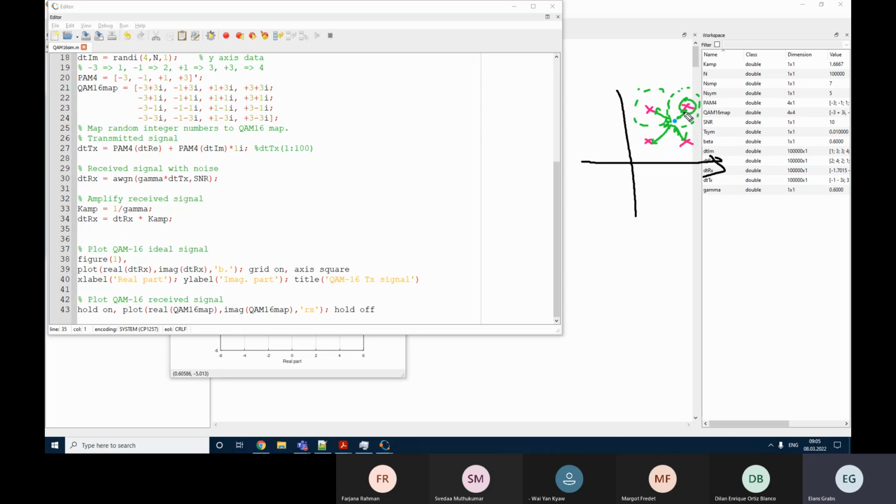But of course, if noise is too high, sometimes a situation can happen like this symbol will be converted into something like this, yes, and it will be incorrectly received. That is actually how errors in communications happen, yes. So we can only make some codes that will make error correcting. We'll talk about these codes later, but for now, we are going to use this logic to demodulate the signal.